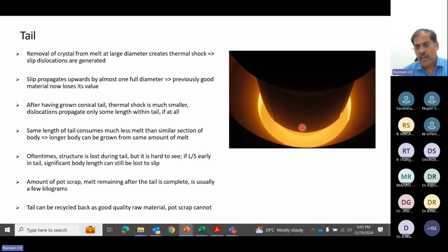Not only the impurities, but also the oxygen concentration varies across the length from top to bottom. You can change the length of the crystal according to the amount of silicon you load into the crucible. And when the diameter increases, because your volume is fixed, say 300 or 400 kg of silicon, the length of the crystal will come down. If you minimize the diameter, you can grow an even longer crystal, even up to 5 or 6 meters, which the industry has already achieved.